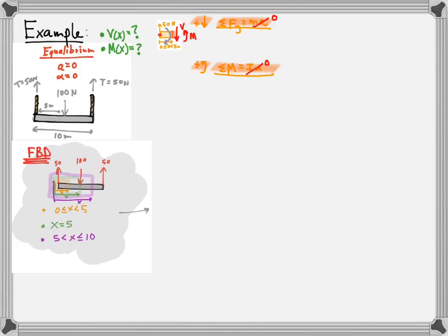So let's go ahead and evaluate these things over here. We're going to look at the forces in the y direction and the moments also. Once again, because of the criteria we described previously, downwards is going to be positive shear and counterclockwise is going to be positive. So let's jump into our force equation here. We've got 0 equals, and we are going to walk from the left side towards the right and account for all the forces here.